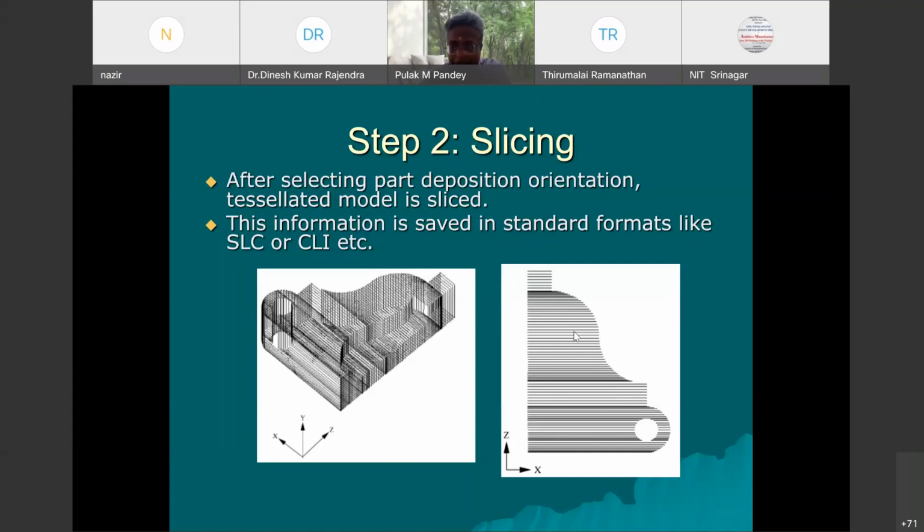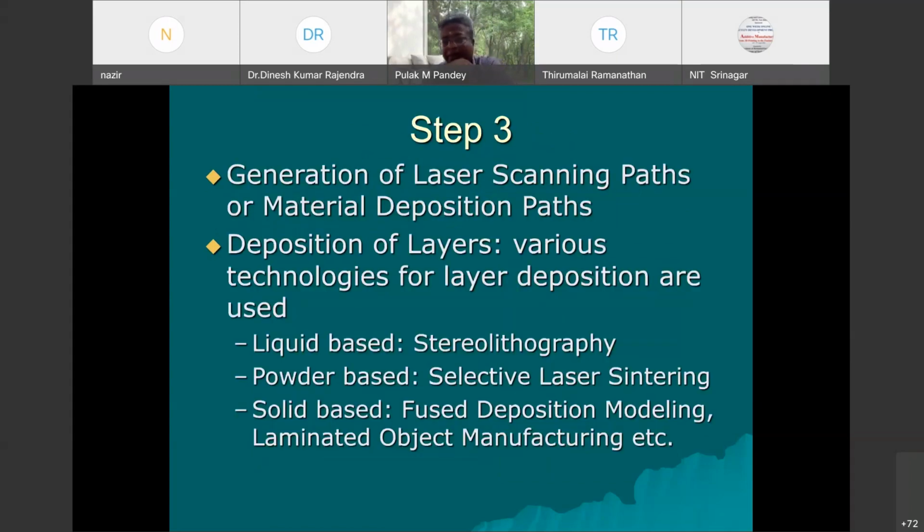Now here, if you really see this picture, you can appreciate that some of the slices are very fine. However, some of the slices are thicker. This happens because you are going to talk about adaptive slicing, correct? Adaptive slicing means you are depositing thicker slices as well as thinner slices in combination, so that you are able to minimize the build time. At the same time, you are able to minimize the stepping effect, so that your surface is smoother. But in reality, you will not find any such system which is able to deposit like this. In one part, we generally use the same slice thickness everywhere.